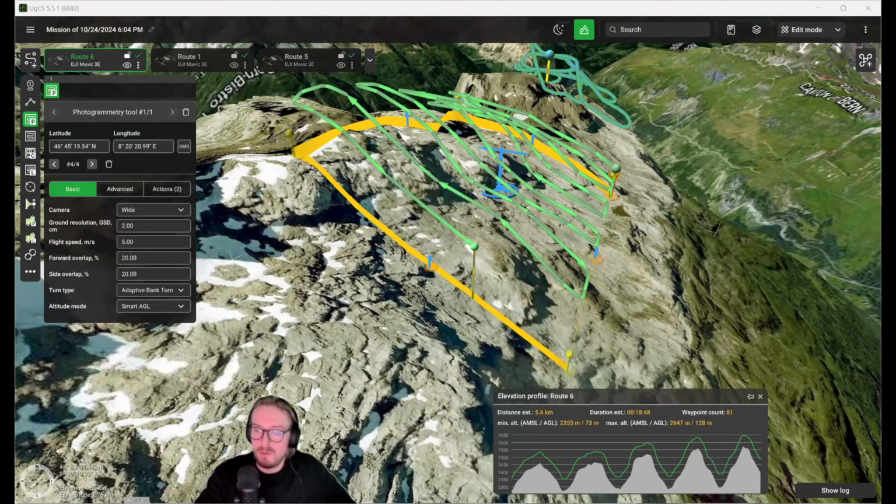Yeah, about ground control points. Essentially the workflow is basically the same as linear photogrammetry. Let's say when you fly with something like Pilot 2 Oblique, it's essentially the same. You just set the ground control points, mark them, and then as you do data processing, you just utilize them.